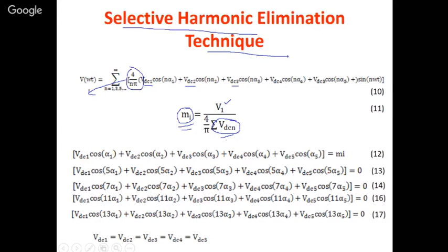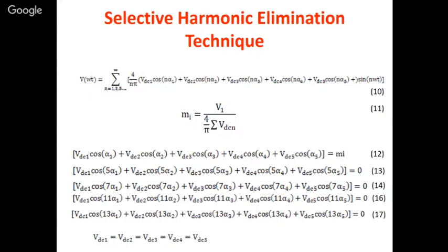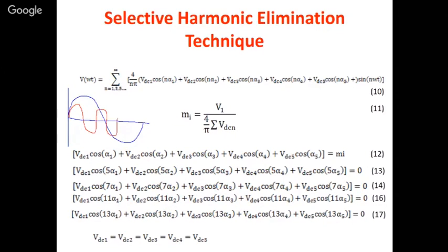When the third harmonic is not there, the fifth is the deadliest. Why do we say that? Say we have an AC supply here. How does the third harmonic occur? The third harmonic has 3 cycles in one cycle of the fundamental, something like this. My diagram is not so good, but anyway, I can adjust it. There are 1, 2, 3. So here, when there is a third harmonic, your resultant output voltage, the fundamental plus the third, will be something like this.